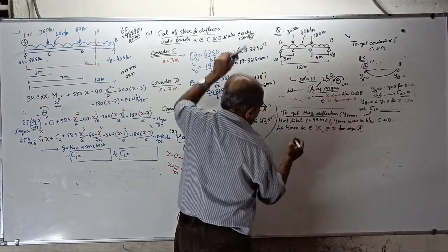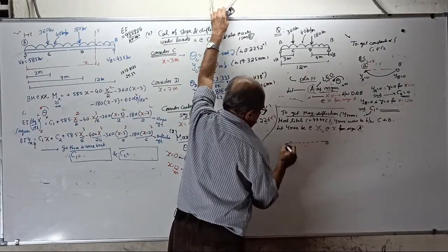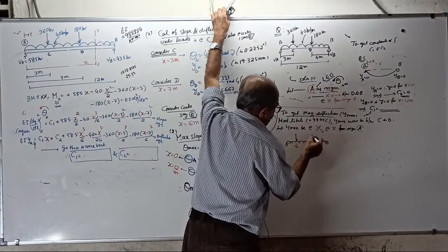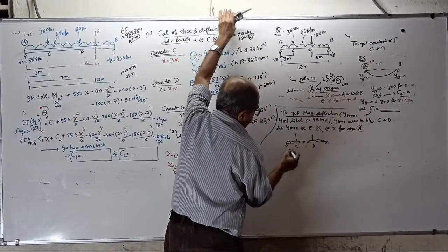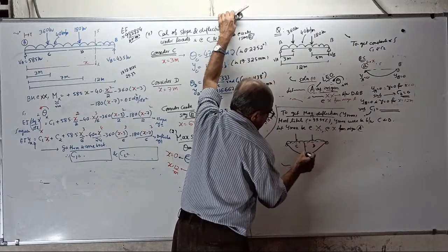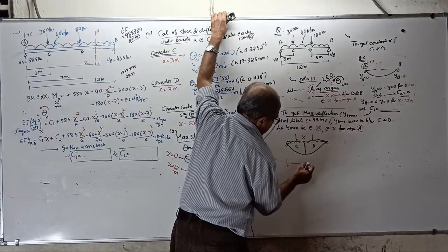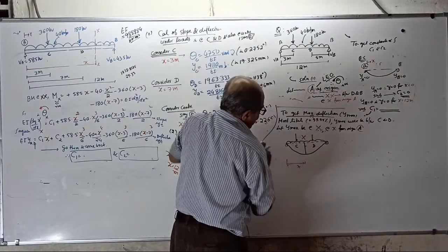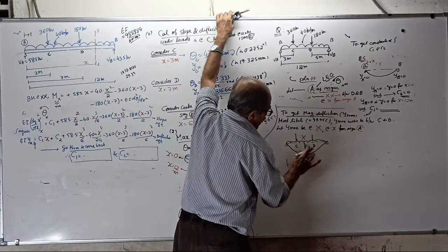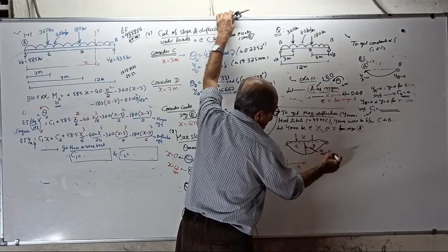We don't know where. This is the beam. This is the UDL. This is a point load here at C. One more point load here at D. Your beam will most probably deflect like this. So somewhere here the Y maximum point is at X from here, and this is your Y maximum. Actually, this is your Yx, this is your Y at X equal to Y maximum.